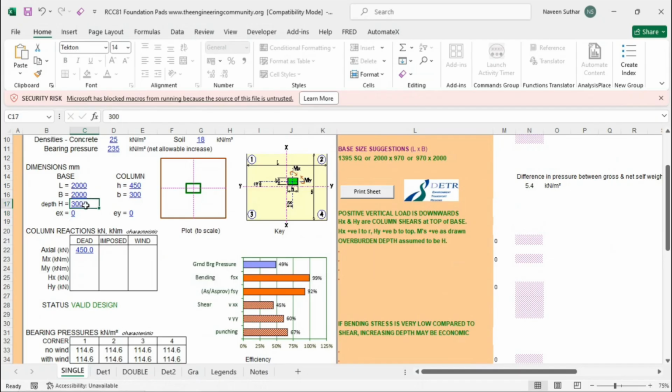So I will recommend you to take 400. Everything is perfect. We have to reduce the bending also. Please try to maintain everything around 50 to 60%. If you maintain it from 50 to 60%, your reinforcement result will be around less than 1%. So you can do the cost effective design for your client or for your company also.